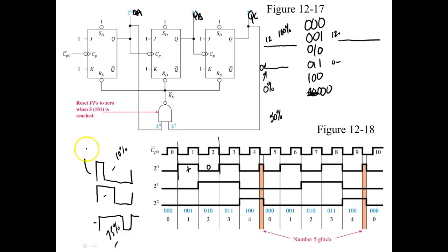The formula is DC average is equal to DC max times the duty cycle. And that's the fraction, so this would be 0.75. Now, why is this important?